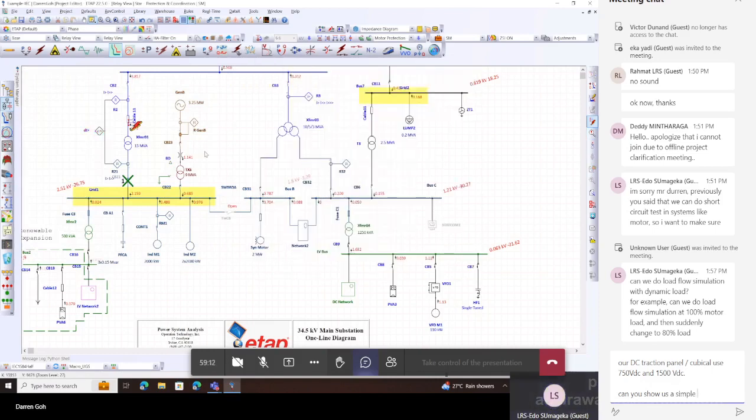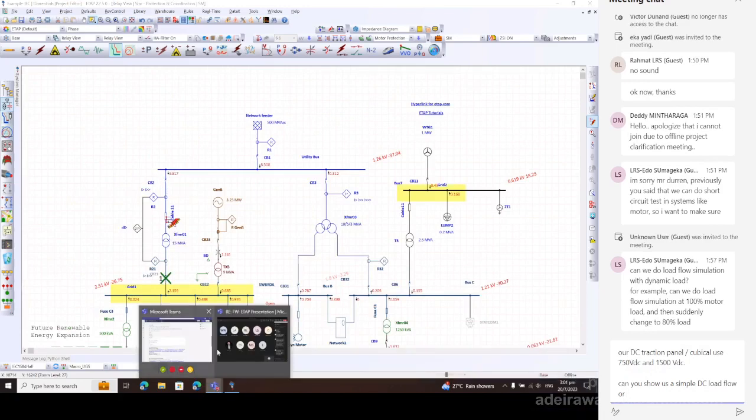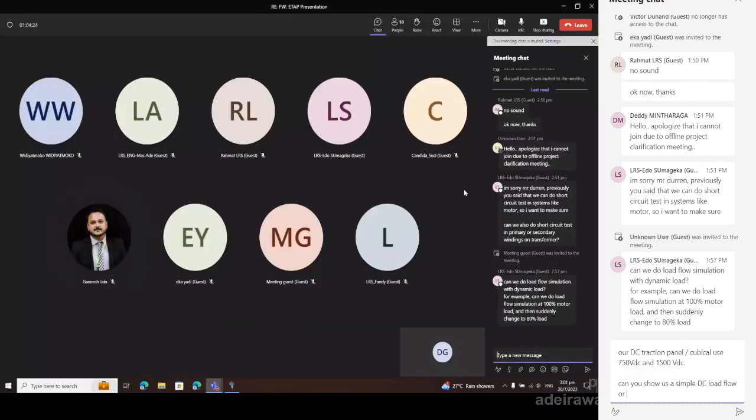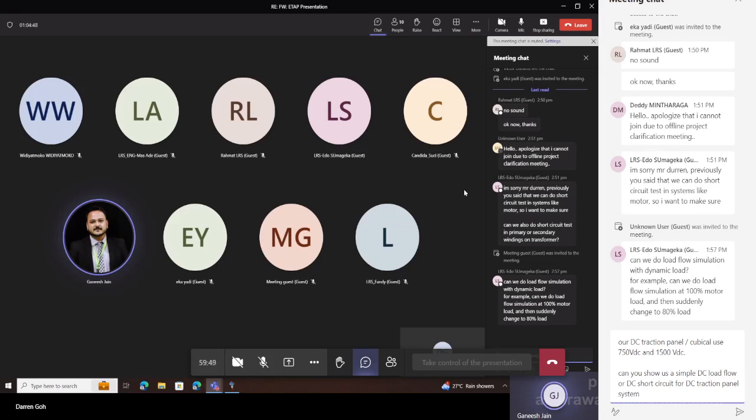That's not possible right now for the sequence operation, to insert the fault inside the winding. Ganesh, do you want to add on to this? That will basically be reflected at the primary itself, right? Just on the line side, we cannot simulate it inside the primary winding. When we say we are inserting the fault on primary, it is at the primary terminal.